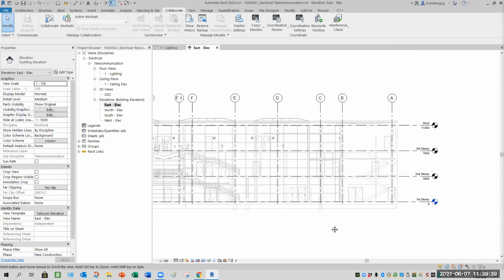So by the end, when we make all the different files, do we need to add in, for example, the first one we made is HVAC, do we need to link the rest of the file to HVAC also? Okay, the purpose we link is to check the location. That means the component you add, there's ceiling involved. Ceiling involved means I must have mechanical, electrical, and fire. Now, why I say telecommunication, if we do wrongly, we got to change again because we haven't added in fire yet. The purpose of collaboration, coordinating them in, is to check, to avoid clash.